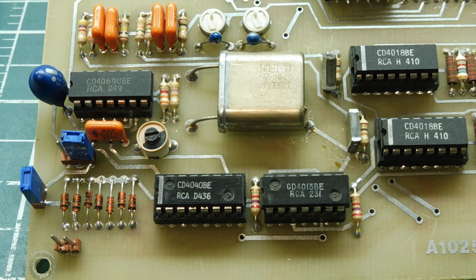Okay, in this video, we are going to have a look at FSK, frequency shift keying. Now in computers, in digital logic, we use binary ones and zeros, and in digital circuits, we use logic ones and zeros, and we represent them as voltage levels. So we have 0 volts for binary 0, and 5 volts for binary 1. Now sometimes we'll use 3.3 volts or as high as 10 volts, and we use these voltage levels, say in UART, so RS-232 or RS-485, or Ethernet, where we send these voltage levels down a copper pair to the destination.